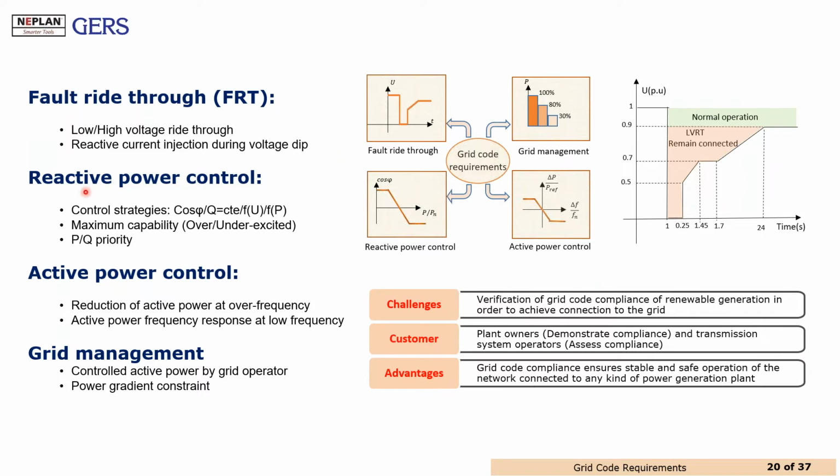Another requirement is the reactive power control, and we have different control strategies. How can we modify the set point according to the voltage level, or according to the active power, or according to the reactive power? We have to consider priorities if we would prefer to inject active power or reactive power, depending on the control system. The other one is the active power control.